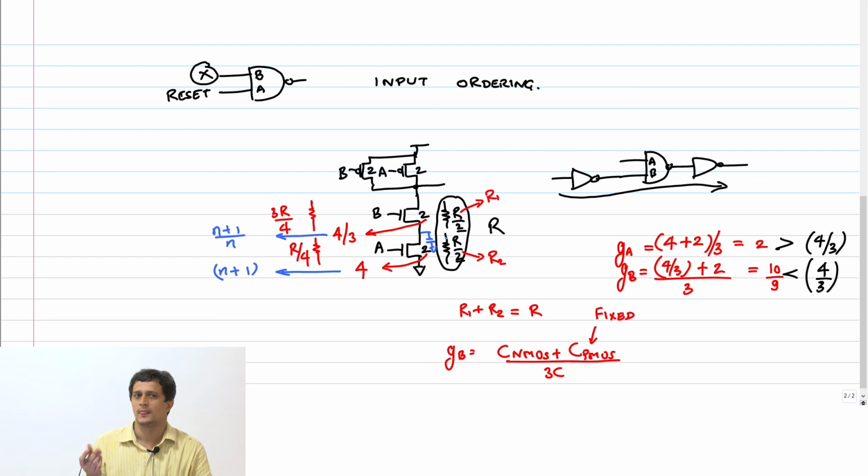That's all. You have to do Elmore delay again to get this number right. And in fact, that in between capacitance here, you have to recalculate a little bit. It may not even be true that it's a shared uncontacted diffusion and stuff like that. So I would just say you have to rely on simulations on the RC extraction netlist. Okay?